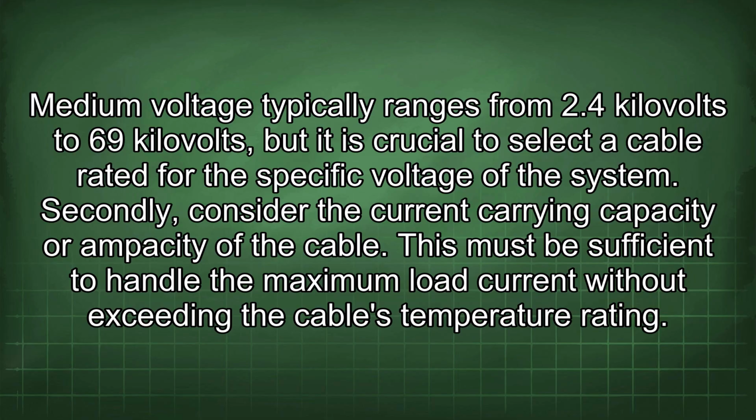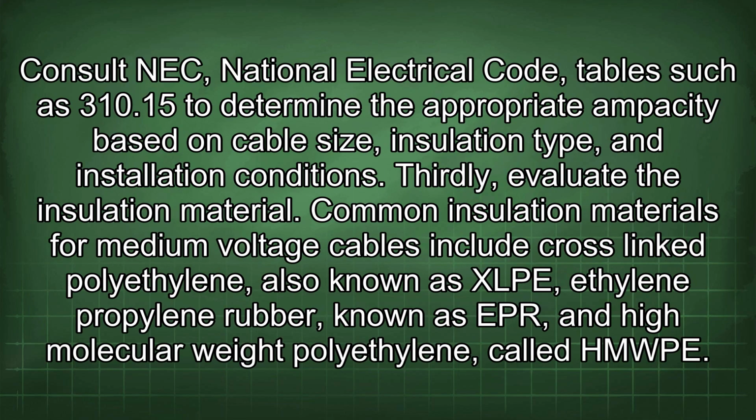Secondly, consider the current carrying capacity or ampacity of the cable. This must be sufficient to handle the maximum load current without exceeding the cable's temperature rating. Consult NEC, National Electrical Code, tables such as 310.15 to determine the appropriate ampacity based on cable size, insulation type, and installation conditions. Thirdly, evaluate the insulation material.